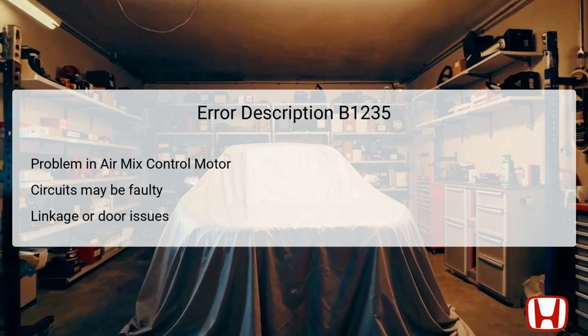The linkage and door also play vital roles. If they become jammed or broken, the motor won't function properly. These issues can usually be found in the dashboard, making them less accessible for at-home diagnostics. Understanding this error is crucial for pinpointing the reason for ineffective climate control in the Honda Civic models.